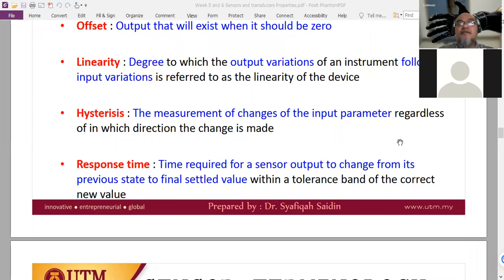Usually it will be the value of 1 over tau, according to when it reaches tau, the time constant. Remember, in circuit analysis for a first order system we have the tau. So when it reaches tau, or about 63%, it can be defined as the response time.